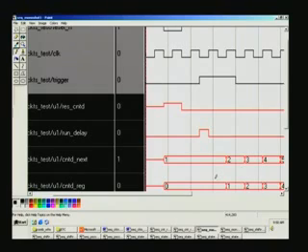Trigger P is nothing more than a previous trigger. That's how we compare the previous trigger and the current trigger, and then decide that it is a rising edge. So the rising edge is limited to the clock period, so it can't act fast. Like this, if you are designing a complicated system such as a programmable controller or programmable logic controller, we may encounter hundreds and perhaps thousands of IOs. In such a case, so many IOs might be on this rising edge direction. So for that you can implement it in this fashion.